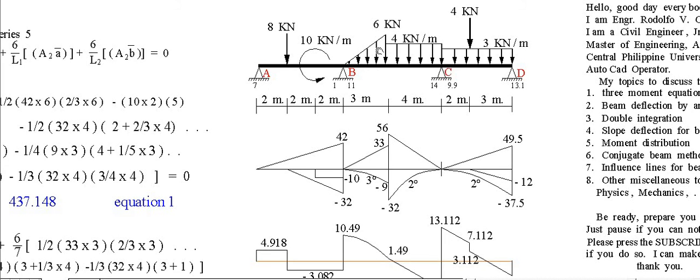Down below, the moment due to the triangular load is 1/2 times 6 by 3, or 9, minus 9 going down. This one pivots to this area. The reaction is 14 times 4. Bring this 14 to the pivot here is 56. The uniform load, the moment is 4 by 4, center distance times 2. 4 by 4 times 2 is 32, negative.